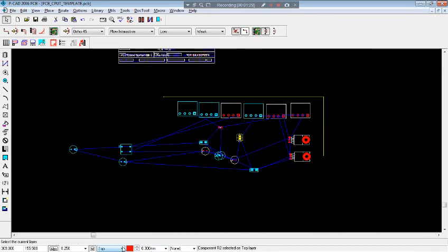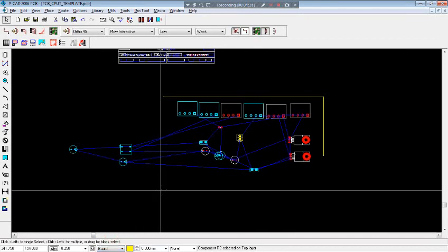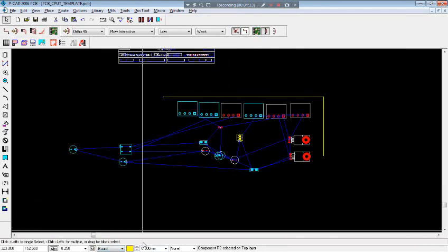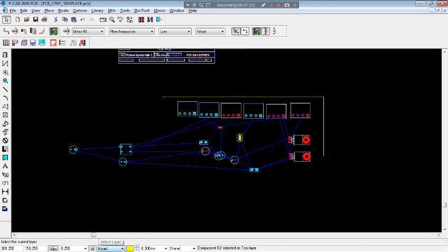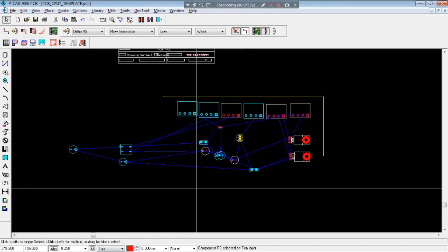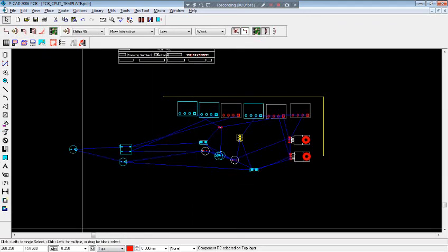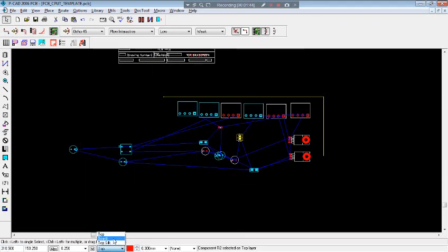No, actually I wanted to go back to the board. I was still busy placing, so go back to my board. Notice it's yellow, then I'll know it's safe. I only picked up now that I was on the wrong layer by saying top, because I realized my eye jumped to the bottom seeing that it was red. I knew that my board is yellow, it's supposed to be placing on the board.